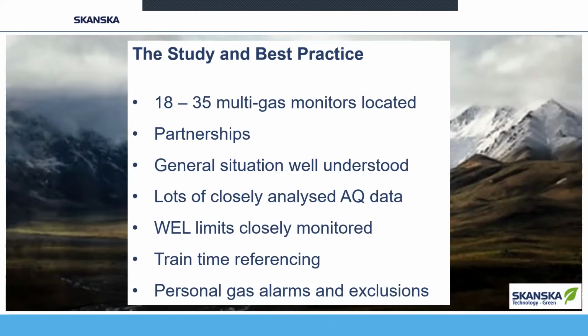We now have a very clear idea of the general situation around the station. We know what our main gases are, we know where our high risk areas are, and we have a lot of closely analysed air quality data. What that has allowed us to do is to monitor areas where we feel that the HSE workplace exposure limits are close or may become close to being breached. And then we can, with that knowledge, begin to find out what times of day and locations that's happened and move people away from there, making sure that people aren't working in those areas at high risk times, so that we can begin to proactively manage the situation.